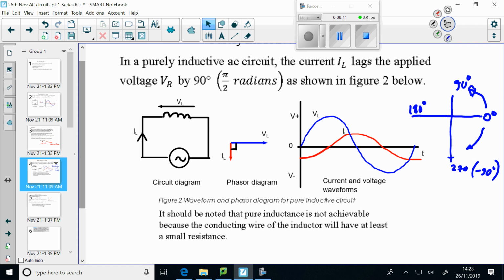Voltage goes high, current tries to go high really quickly, but makes a big back EMF, so it makes that full 90 degree phase shift in the current. All right? All happy with that? So, it must be remembered that inductance causes current to lag voltage by 90 degrees. Now I've got an easy way for you to remember this in a minute coming up.